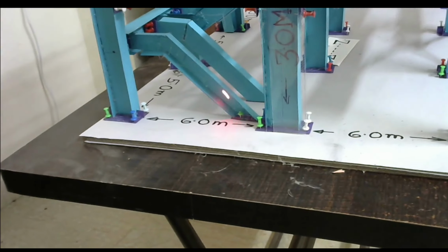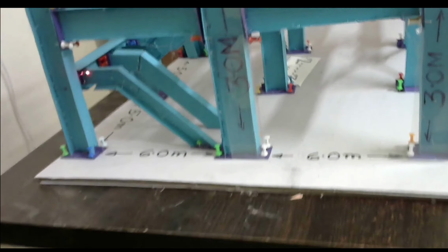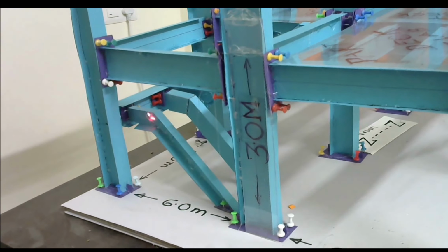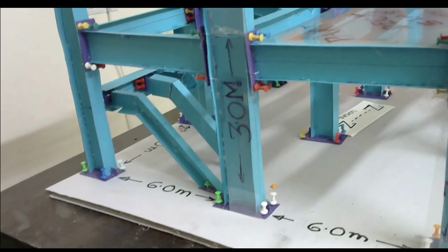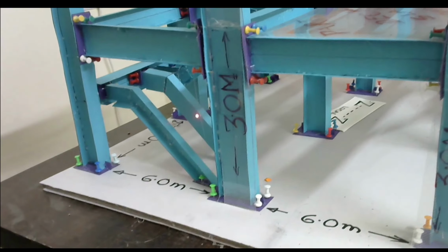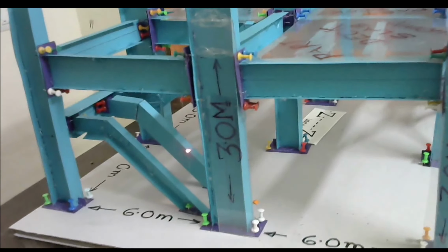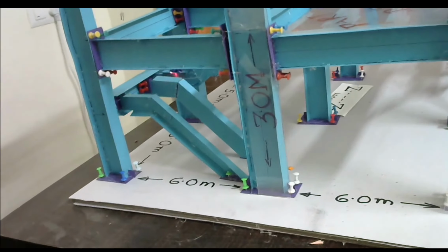Now let us come to the stringer. Stringer is a simply supported beam. It is a cleat connection here. We must provide a slotted hole here, so that it does not take part in resisting lateral movement, because it is a cross type of member. If you leave it like this, it will obviously start resisting lateral forces, and we should not let the staircase do that. Staircase is one of the main elements for escape of people. So we must provide a slotted hole here while releasing the fabrication drawings. So these are simply supported beams.